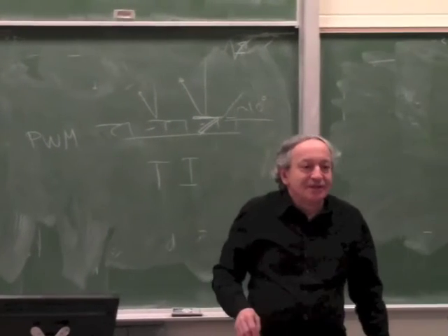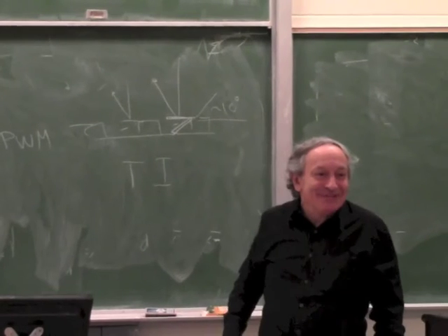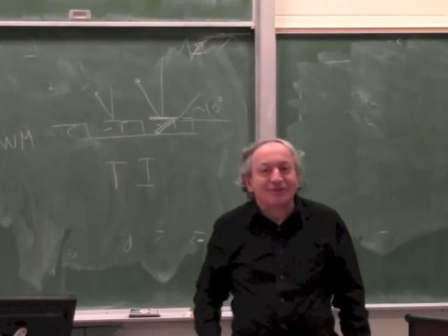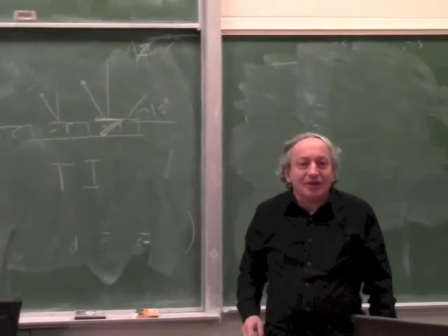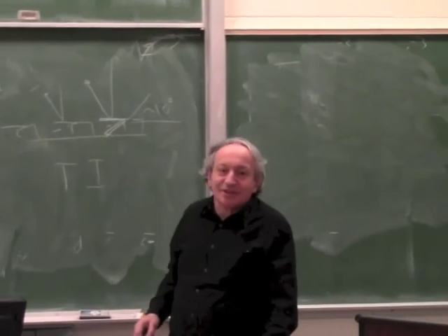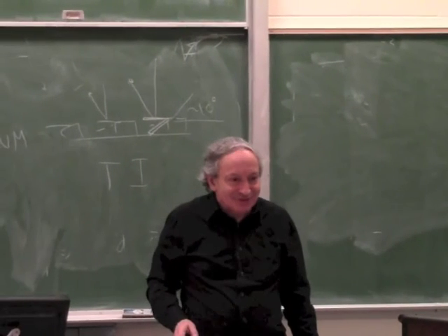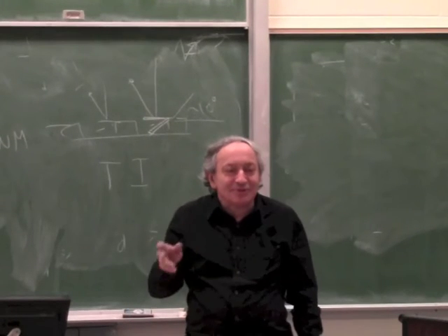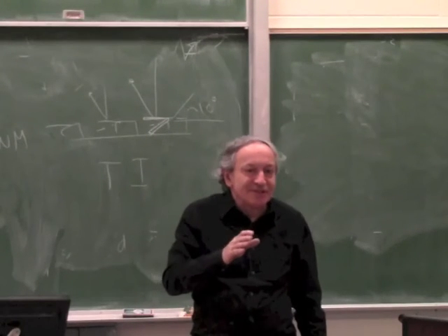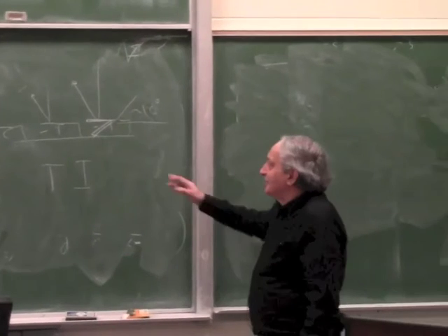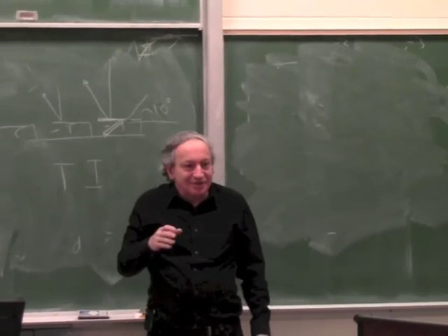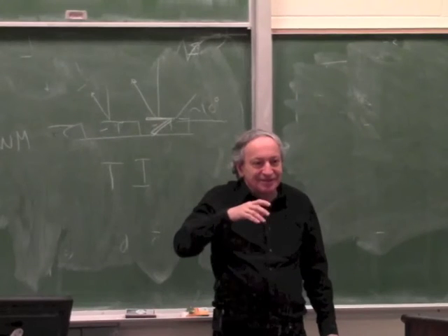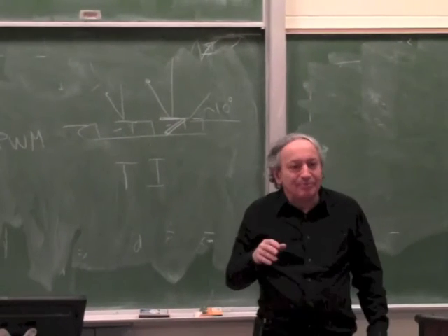Yes? How long do they last? A long time. Because aluminum has finite... Okay, so there's a lot of tricks here. Aluminum usually is a very bad material for fatigue, one of the worst. But if you make it very, very thin and it's the right processing, blah, blah, blah. But the interesting thing is it's not silicon, because the best thing to make these mirrors is silicon. But silicon cannot take a very big stress. So it actually turns out to be better to make them of aluminum.